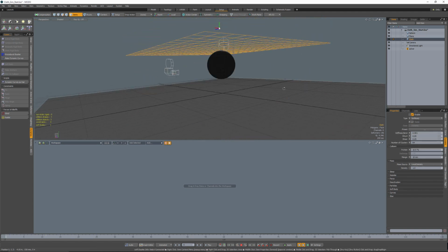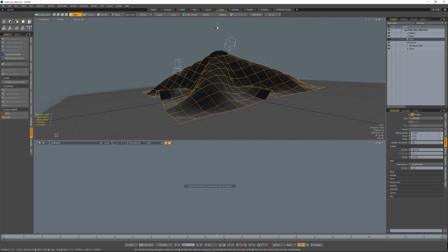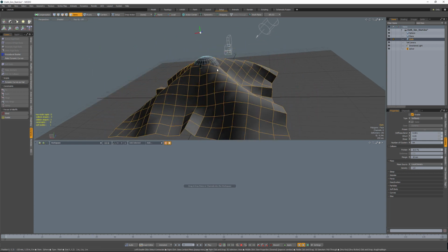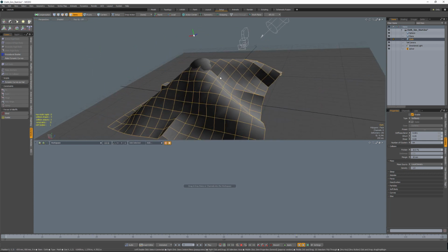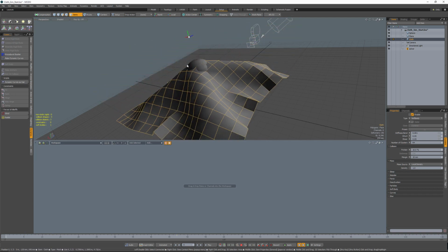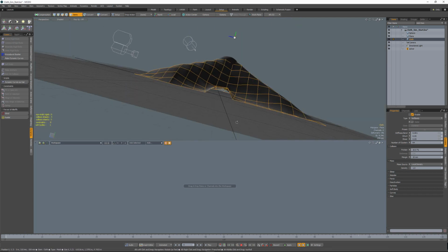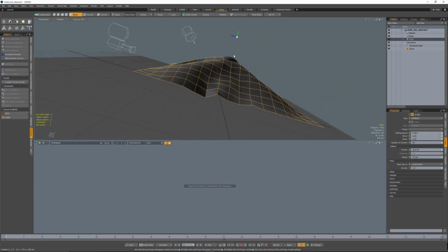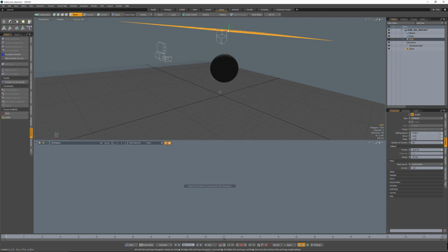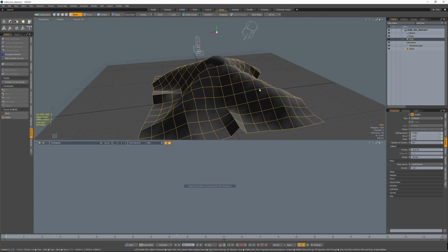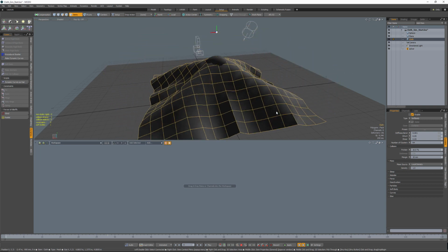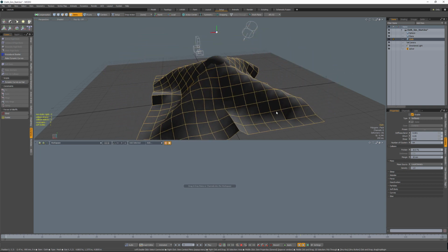And now that we have a little bit of the feel that we're looking for, what I'm looking at here is just the general way that this does bend where I do have the resolution. So you can see I have the resolution through here to see this arc shape. I don't have enough resolution going down these diagonal edges. So we'll have to actually start increasing the resolution of the solve and of the mesh in order to get more depth. So, taking step one, we've gotten our things adjusted. Now we're going to move on.